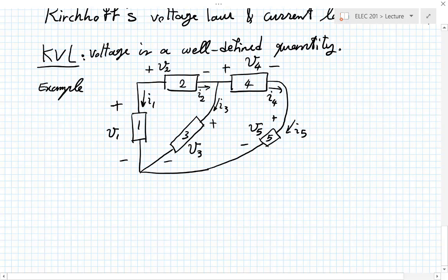That's really all there is to it. What do I mean by that? Let's take element number 1. I said the voltage across it is V1. And this is how I chose to indicate the polarity, meaning that if V1 is a positive number, indeed, it means that this side is higher in potential than this side. And if V1 was negative, then it was the other way.